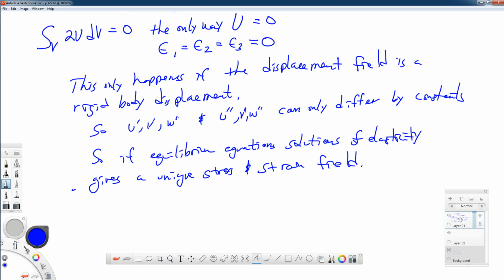So saying that the displacement fields are unique for a given elasticity solution also has some implications to our material behavior assumptions and their stress-strain relations. So if we find this, we don't have to go hunt around for another set of strain fields that also satisfy equilibrium. Once we have it, we've got it.